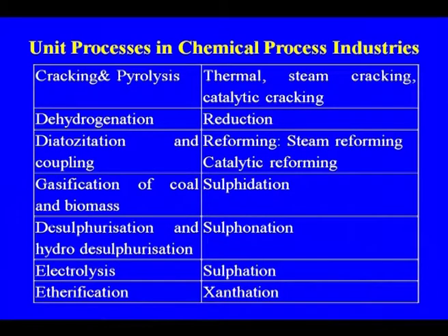Other unit processes that have now become very common are cracking and pyrolysis, dehydrogenation, nitration, coupling, and the gasification of coal and biomass, desulfation, hydrodesulfurization. There has been a lot of change in the case of desulfurization and hydrodesulfurization, especially in the petroleum refinery industry, to meet the norms of the various fuels, whether gasoline or diesel, or to meet the requirement of the feed for the various processes.